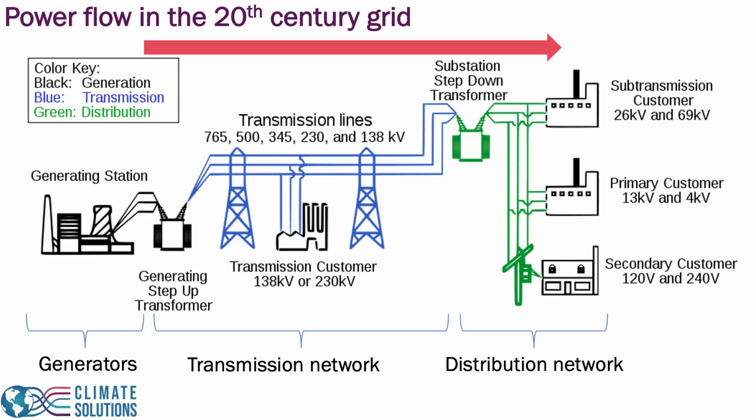Once the power flows through a transmission network at high voltages, it is then stepped down through transformers to lower voltages so that they are distributed in our local neighborhoods. This is done in order to ensure safety. High voltages can be quite dangerous, and they are not very safe to have near where we live and work. At these lower voltages, now currents are higher and they flow all the way to the end consumers.